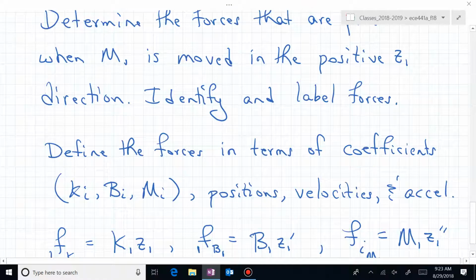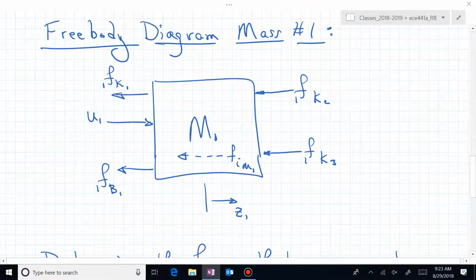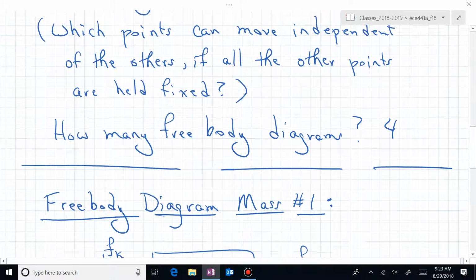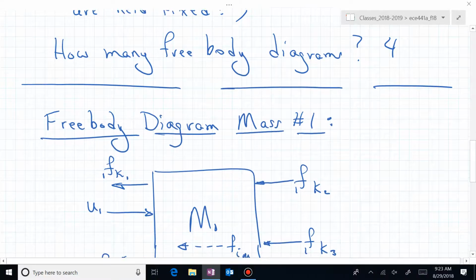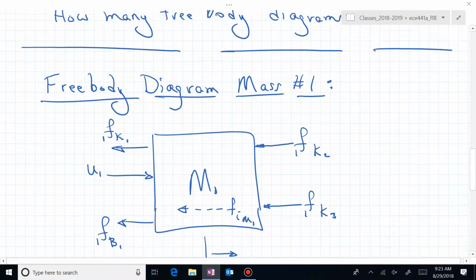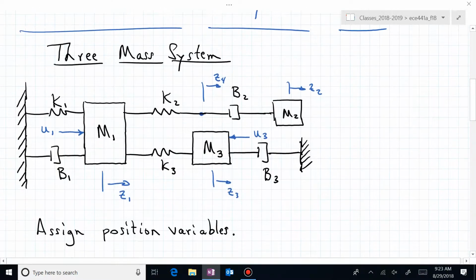It's K sub 2 times something. Now what is going to produce a positive force to the left relative to this overall block diagram? Now we need to consider both ends of that spring. And how do we define the force? K2 times something, such that its two ends, when they produce a positive result, give us a positive force to the left.